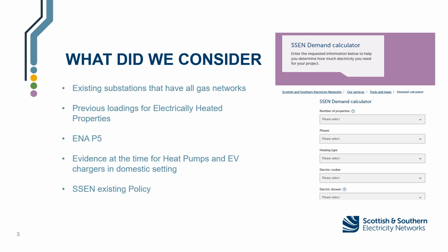In order to do this, we had to look at our historic data that has been used for many years. However, in doing this, we also realised that the way we use electricity 20 years ago is completely different to the way we use electricity today, and we have to start considering things like heat pumps. The fact we're less reliant on gas these days, so things like electric cooking, also electric vehicle charging. These all add significant loads to domestic property, and especially to our distribution network. And all these things need to be considered when we're considering any demand calculator.